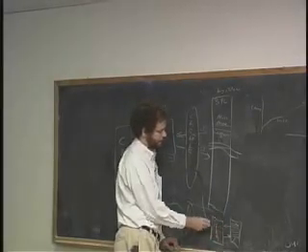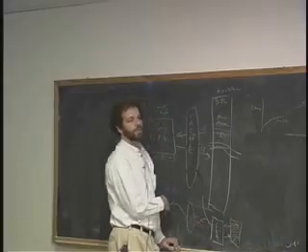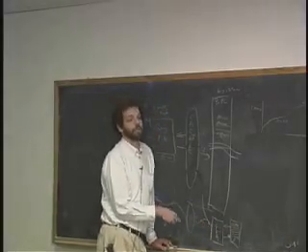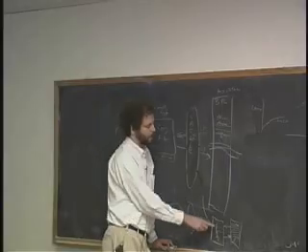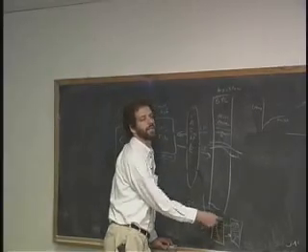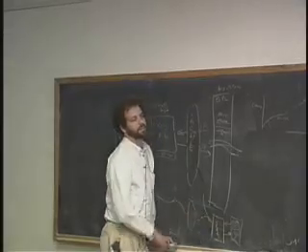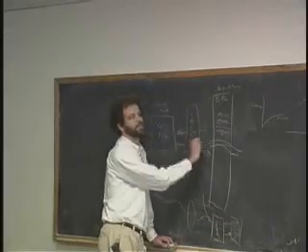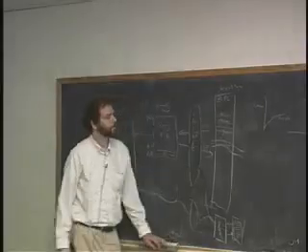And then on the other side, there's reads and writes that are going in from the processor, typically at a much lower rate. And so VRAM is specialized to allow the right-hand port to do that all the time and the left-hand port to do it less of the time, whereas this is sort of a single-ported system here.